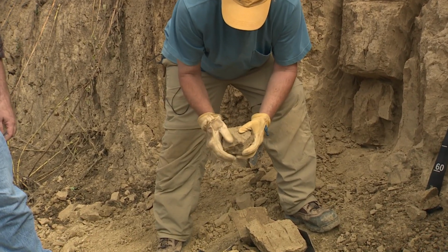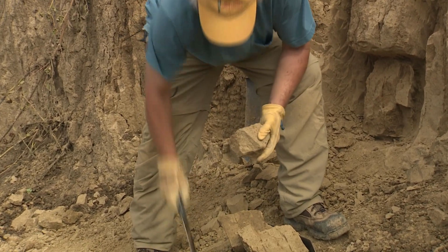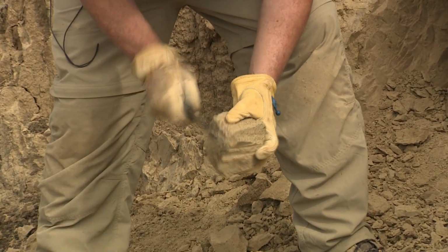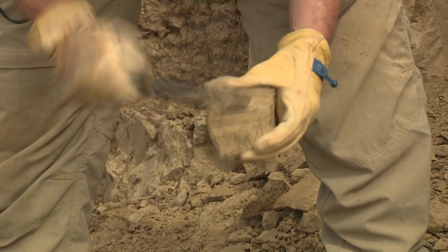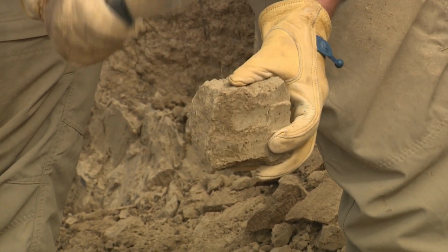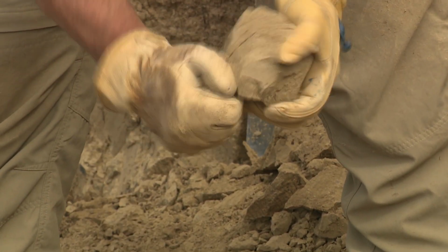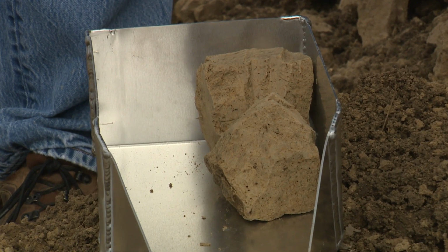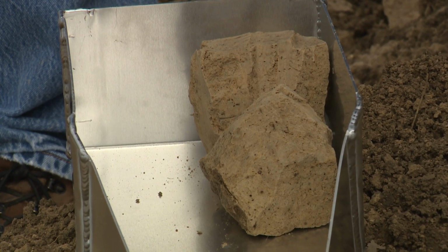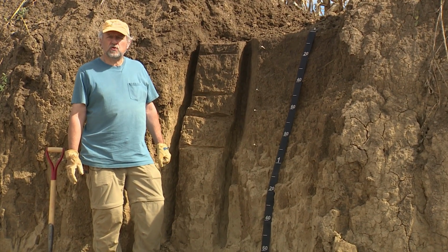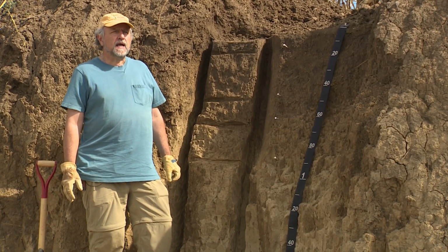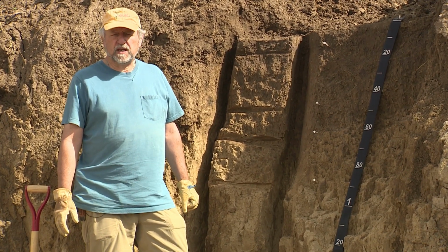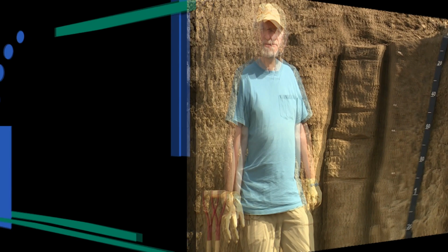The objective is to extract a chunk, roughly the size of a potato, from the soil and keep it intact, and safely preserve it and transport it to the laboratory for analysis. To retrieve that sample from the soil, you first of all have to pick a representative site. It is the preferred method to be used, and it is widely usable across many soils, many conditions, but there are some circumstances for which it just isn't